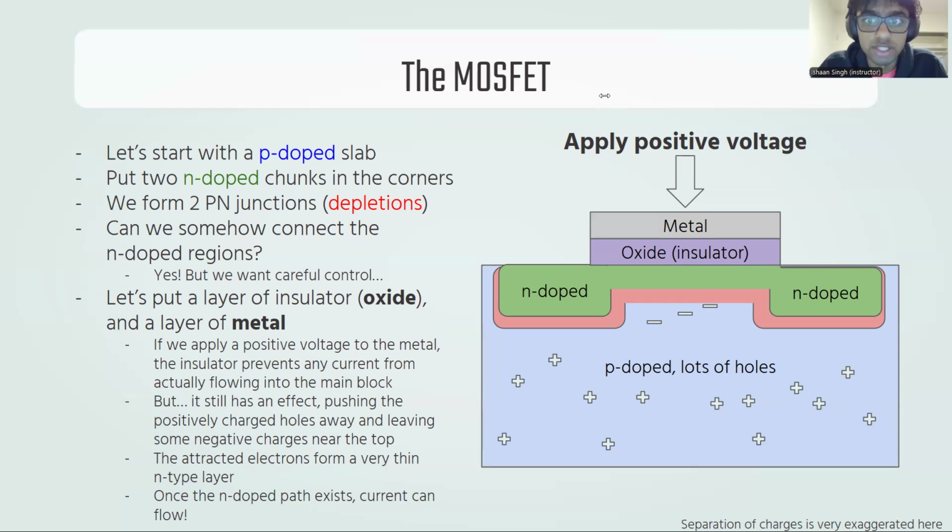That's called a PMOS transistor. So this is the NMOS transistor. The opposite of this is the PMOS transistor. And when we combine them, you get a CMOS inverter, complementary MOS inverter. And that is the basis of all digital logic. That's what lets us do binary things. Not the diode, but really that's the thing. But we'll get to that.